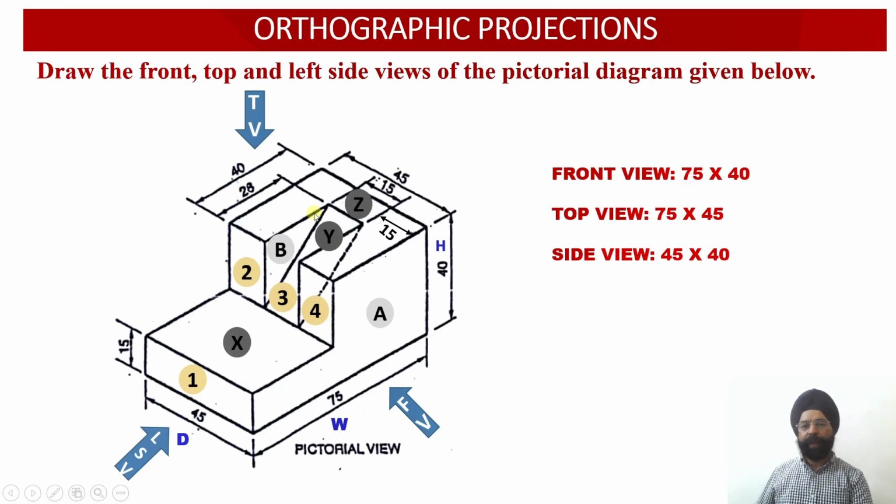But there is a special characteristic about surface 3, which happens to be a slant surface. Because it is inclined to the profile plane, we are again going to get a rectangular projection, similar to surface 2 and surface 4. But we can observe from this isometric 3D projection that the length of surface 3 is much bigger than the length of surfaces 2 and 4.